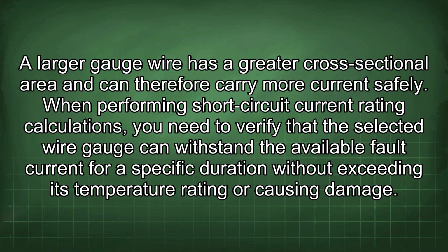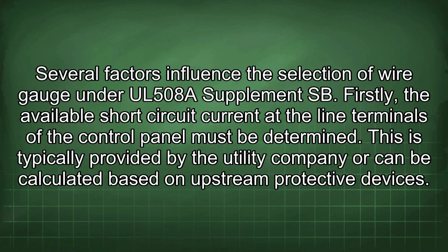When performing short-circuit current rating calculations, you need to verify that the selected wire gauge can withstand the available fault current for a specific duration without exceeding its temperature rating or causing damage. Several factors influence the selection of wire gauge under UL508A Supplement SB.